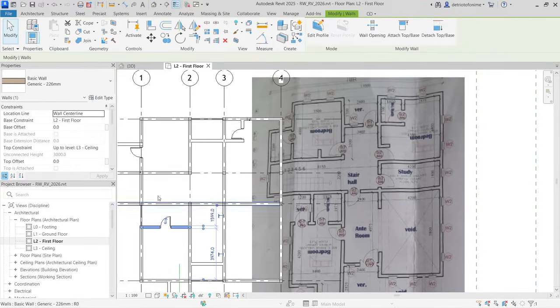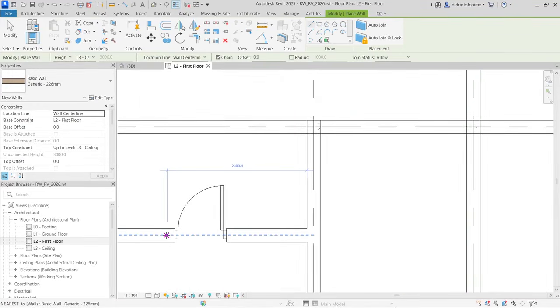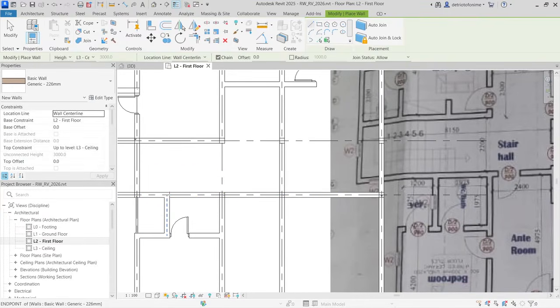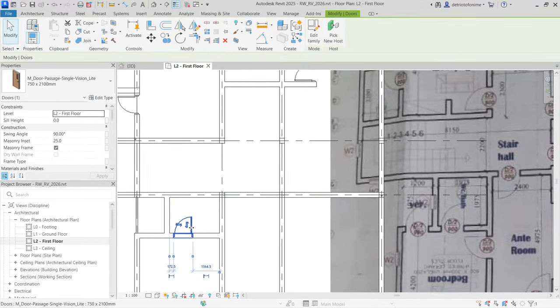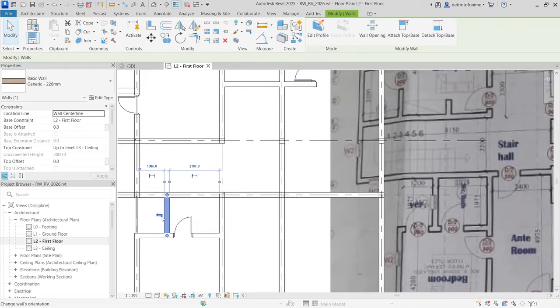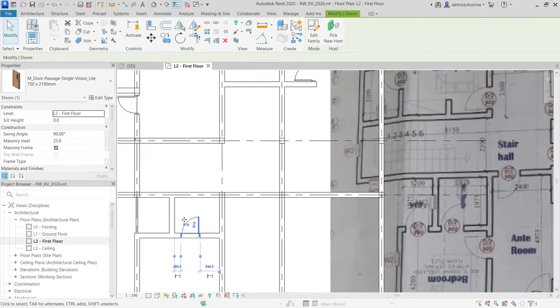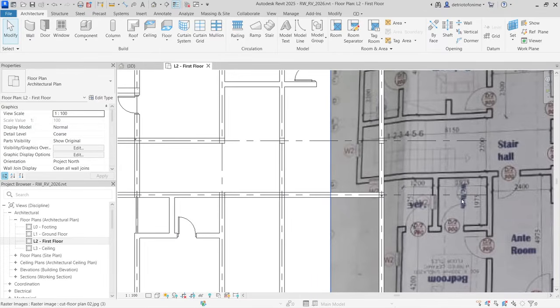But in order to finish this, you have to select this and create another architecture wall. Notice there's a wall here that leads to the veranda. We completely forgot about this wall. Just pick one here and join it this way. So we can move the door a little bit. So there we go. It says here that it's 1975, so we can choose this to be 1975. It clashes with the door, but do not worry, just move the door a little bit to one side. You can press spacebar to fix the orientation of that door. What they have here on plan is not even correct, so let's have it this way.